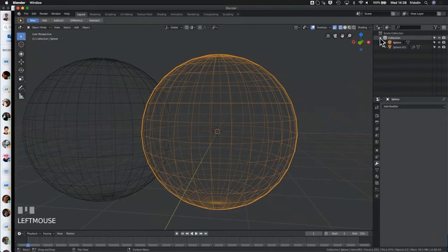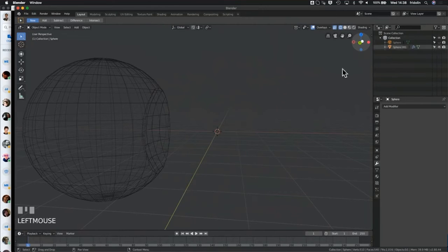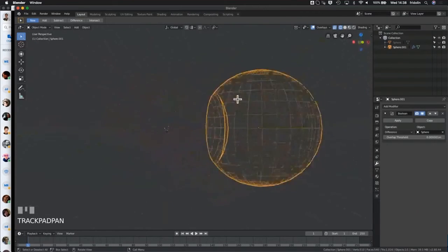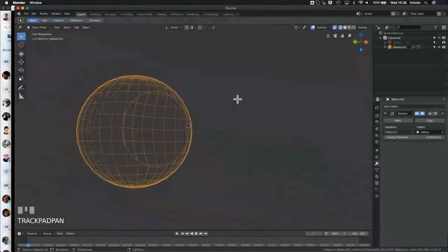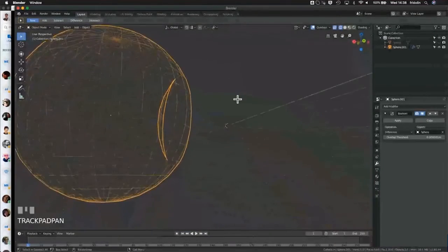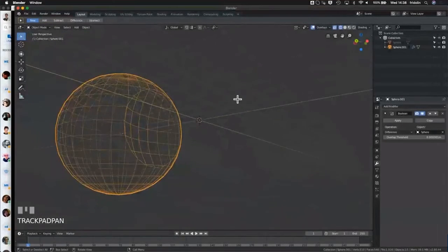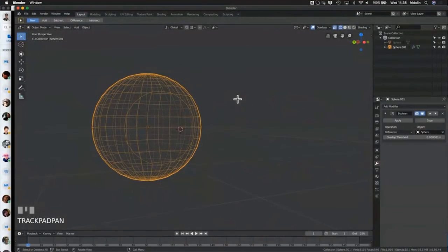So if we go up to here on the top right of the whole screen, not just the 3D viewport, we have a list of all the things in the scene, and we can see the one that we've currently got selected as it's highlighted a little bit in orange. If we make that invisible, then we can now see that we've created this kind of Death Star effect by having a set of two spheres and subtracting one from the other using a Boolean operator.